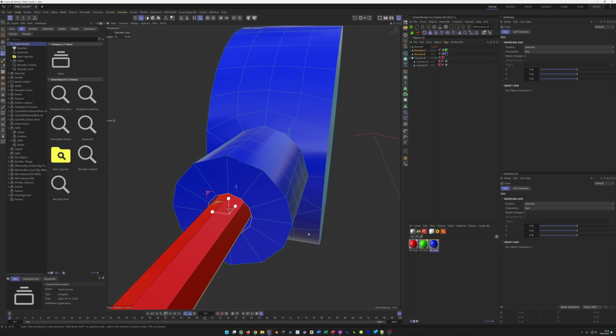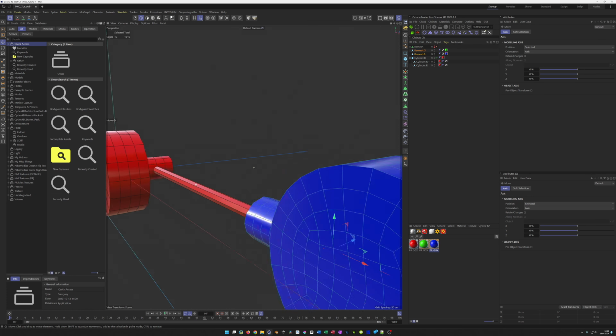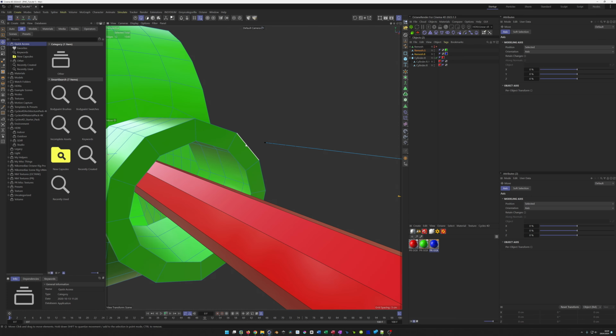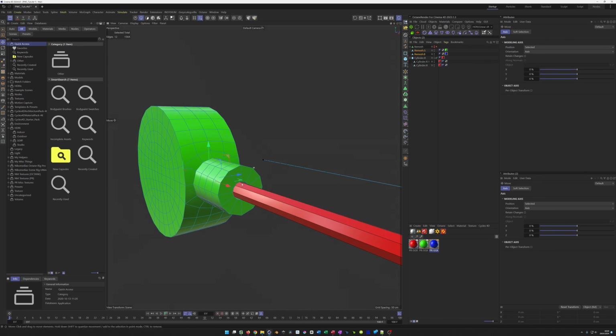Let's hold the shift key so I see it on 50%, 45%. Let's go 50%. Okay. Then E for the move tool. Hold the control key and simply drag the edges to the inside. Now it looks like we would have a solid thing here. Nice. On the other side we do the same. U L for the edge selection. T for scale, scale it down to 50%. Fine. E for the move tool, control key, and come in. So, wonderful.